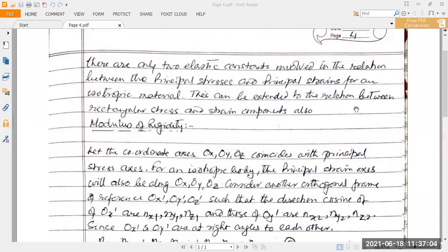That stress can be shear, tensile, or compressive. But if you design your member according to the average stress, it is vulnerable to stresses higher than the average. So you have to know the maximum stress and the minimum stress, and design according to the maximum stress. Stress cannot be measured as maximum or minimum across a section where there are an infinite number of points involved. It depends on the size of the cross section, and you cannot measure it that accurately. So you have to use equations to calculate the maximum value of the stress when necessary.